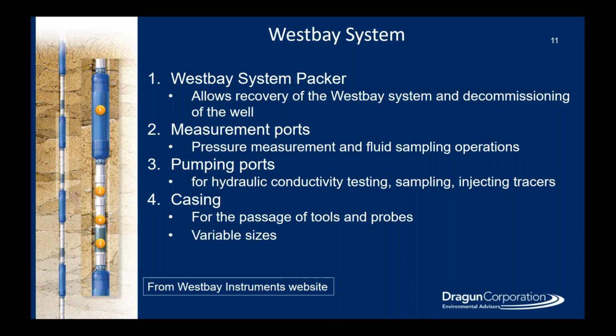And so this packer system can be lowered down the borehole, and you can see on the left-hand part of this, the blue areas are a bladder that you fill up with air, and it seals tight to the side of the borehole or to the side of the casing, and that isolates the spot between the packers, and you can collect a sample from the ports that are installed within the system there.